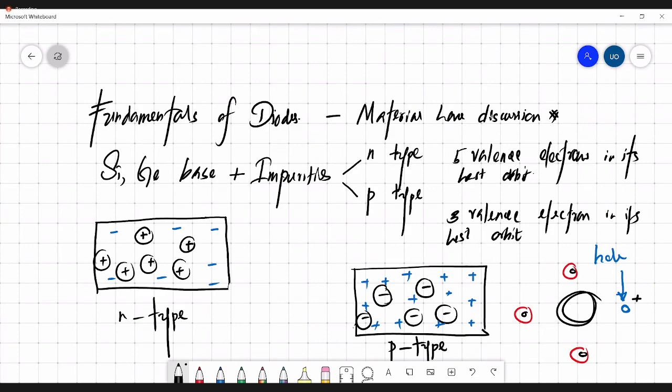So why is it negative actually? Where we have a hole, one electron from silicon, which is in its last orbit, has basically linked to this impurity. If you draw this covalent bond, there's one from silicon, there's another one from silicon, but in this particular case, you don't have any electron to create a covalent bond.